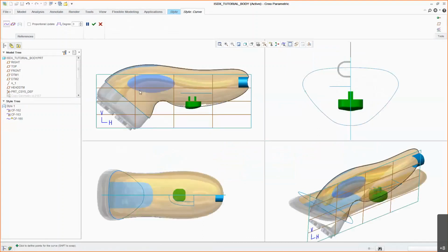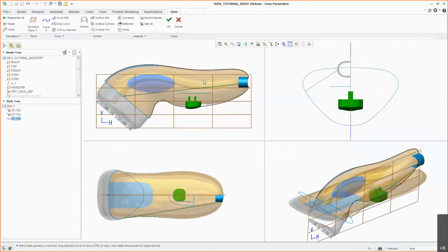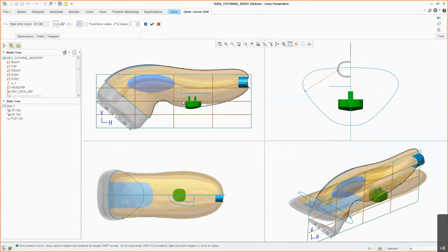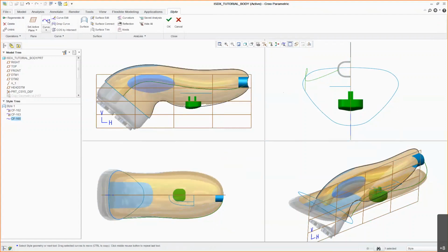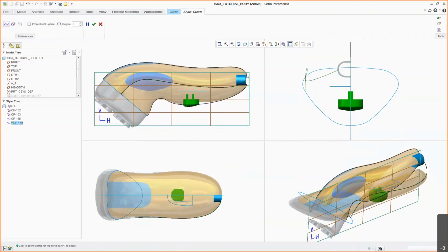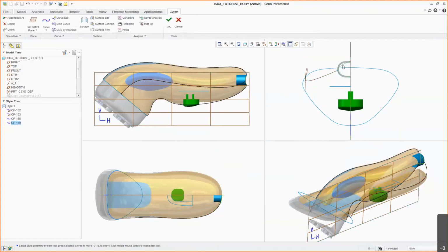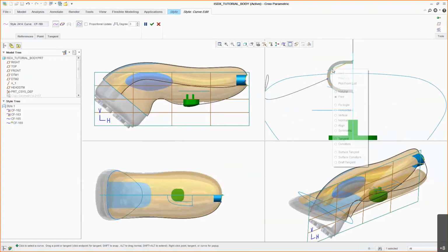So, to look at a free curve, if we want to do a different view, you have this option for a multi-dimensional view. So you can see in the first dimension, if you want to bring it from that start point to the end point, and you want the middle to be somewhere along that parting line, you can pull the normal surface, change that magnitude so that it fits along, and then move it in the next dimension. So here we still have it situated at that end point on that hard dimension, but we're able to define that normal very precisely to have it follow in that other dimension as well. So here, as you're creating a curve in the one view, you can see it appear in the other view, and then make those edits in the view that's easiest for you.